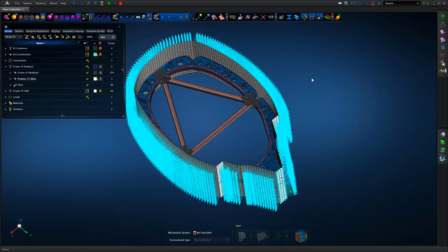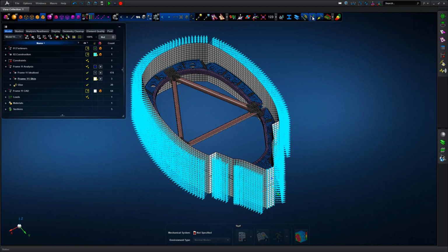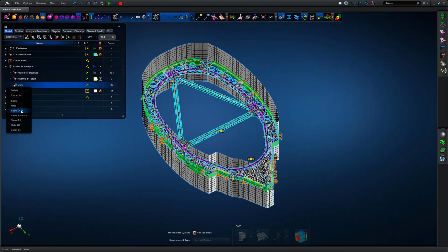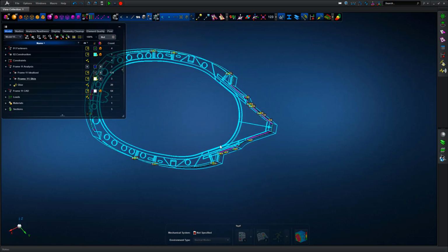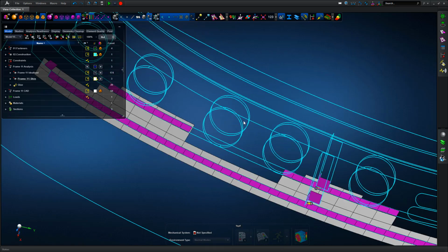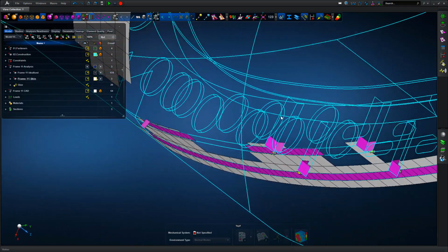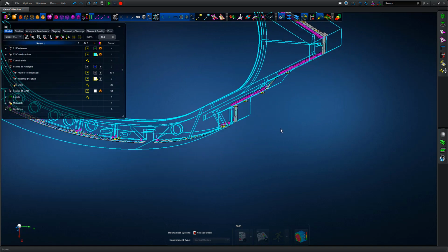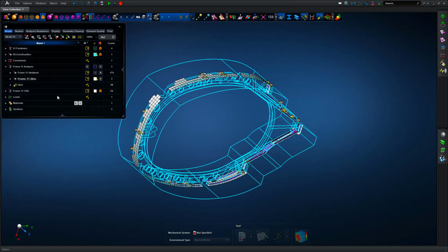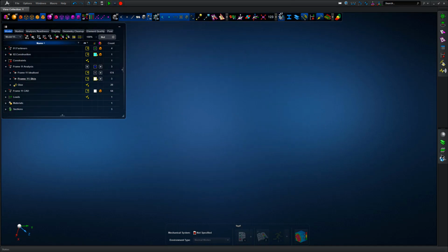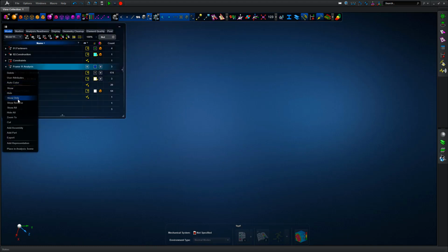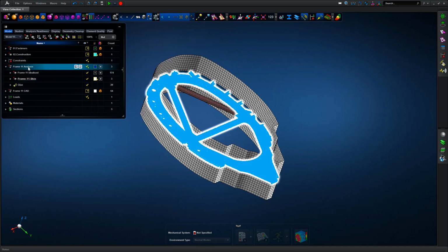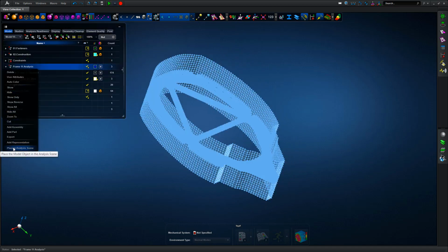So once we've verified and potentially exported the model, we can integrate the analysis assembly into a larger definition. So in this case, we've got a fuselage skin defined, and we glue the original assembly into the skin definition, and again, one of the webinars we've looked at goes over the glue technology from a mechanics perspective in terms of load transfer, both for force and moment.